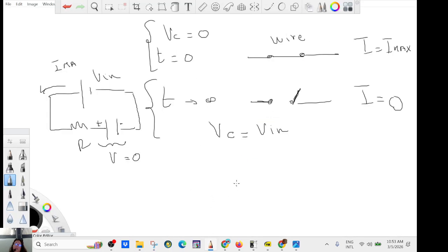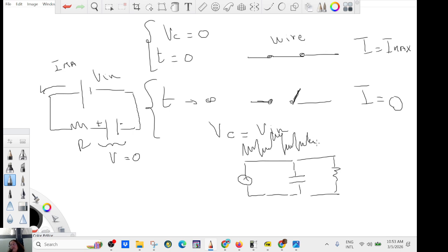Because it attracts AC. So if you have a low pass filter, you have the power supply here, and you put a capacitor here and you have a load there, and you have a signal with low frequency and noise at high frequency, all the high frequency will be dumped through the capacitor there.